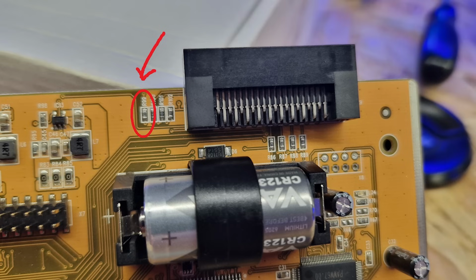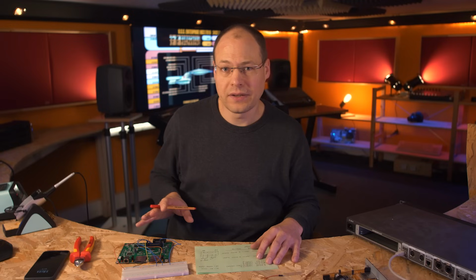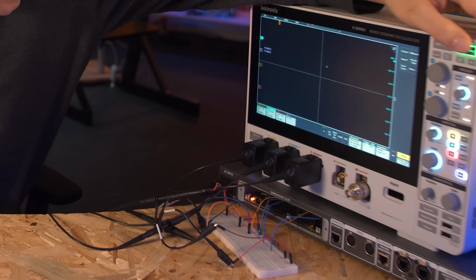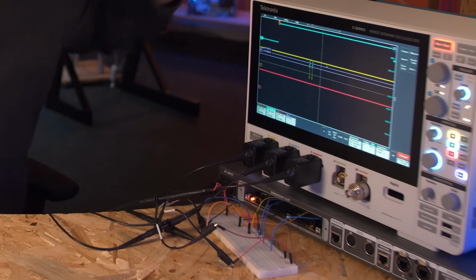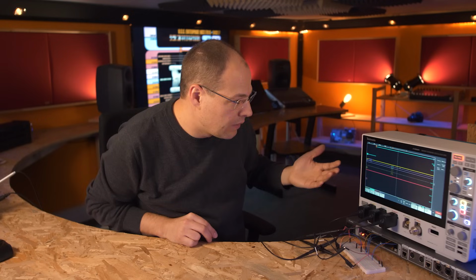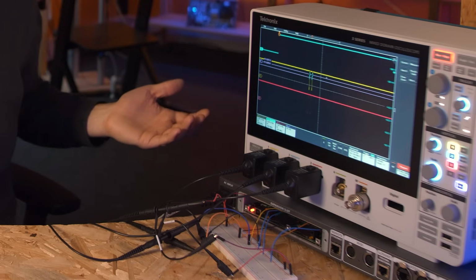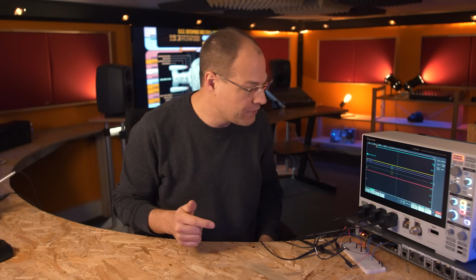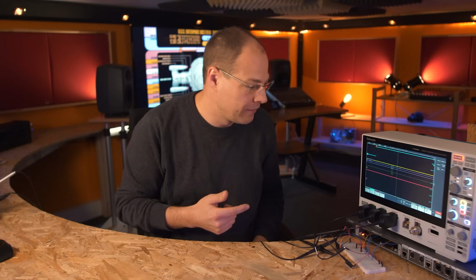Resistor R99 has a 330 ohm. And up to now I did not have a look at this signal, and so I will check this line with my oscilloscope, maybe another communication channel. And it triggered and it stays high, so it's only a card enabled signal. Okay, so that's quite easy to implement in our code. So we have to hook up in Quartus and set the signal to high.